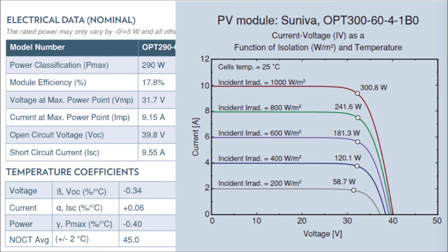The solar panel too has an ideal operating voltage and amperage, and in the past, this would lead to a very difficult discussion about keeping the solar panel away from shade at all cost. Maximum power point tracking, how the inverter operates the module at its voltage and amperage level, will reappear in the inverter discussion.